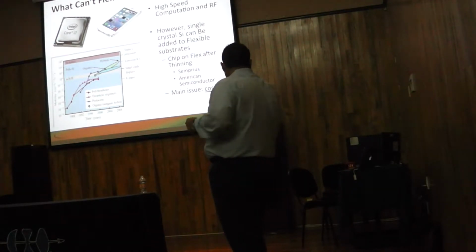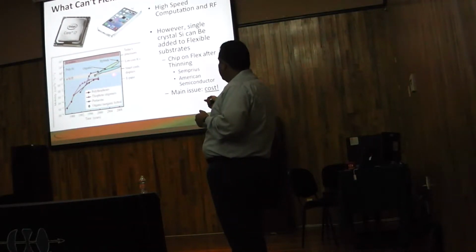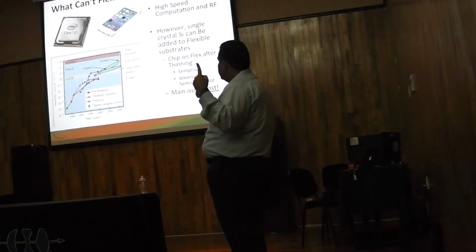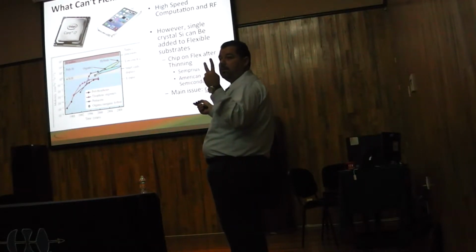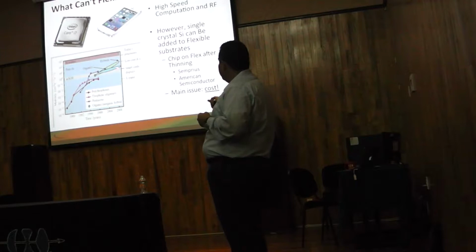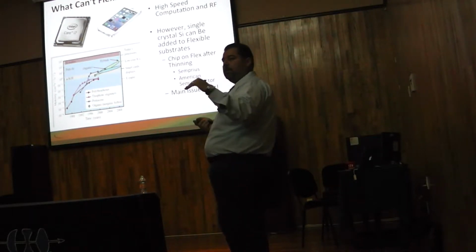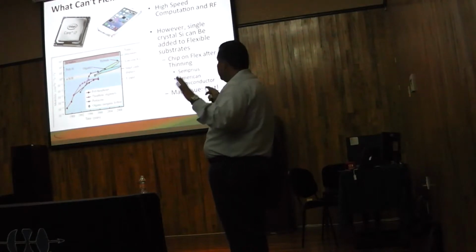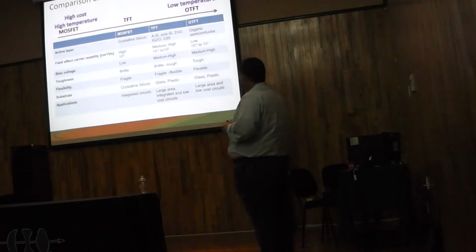If you have a computer, your screen is actually made out of amorphous silicon. And you can see that the mobility for amorphous silicon is in the order of 1, okay? Compared with silicon in the Intel chip that is about 1300. So it's 1300 times higher. For most of the organics, the mobility is about 10. Okay, so it's very difficult to have an organic material that will do computing and operation at the rate that silicon achieves. So forget about flexible electronics with high-speed computing with Intel.